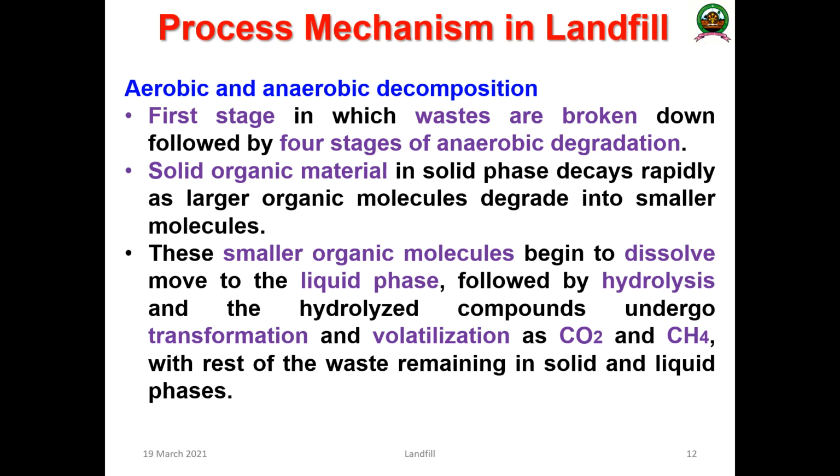Then the mechanism of landfill operations. There are two important things. One is aerobic decomposition. The next one is anaerobic decomposition. These are the microbial processes which are very, very important. The first stage is where the waste is broken down, followed by 4 stages of anaerobic degradation. All the waste that is dumped in the site or collected will be broken down into smaller forms by anaerobic degradation. The solid organic material decays rapidly as large organic molecules degrade into smaller molecules.